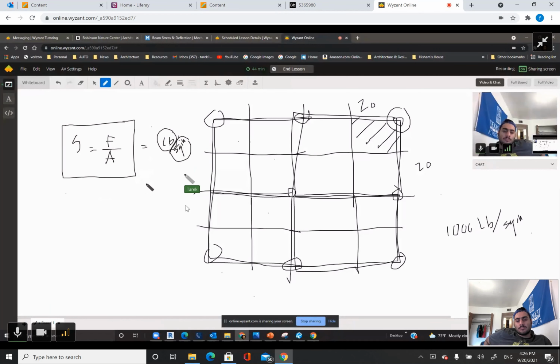Right? So, if I know the force, and I know the stress, which is the carrying capacity of the concrete. Remember the foundation that they give us, they use 4,500 PSI concrete. The same thing, that's given, that's the property of the material. I can determine how big this column needs to be to carry this force.